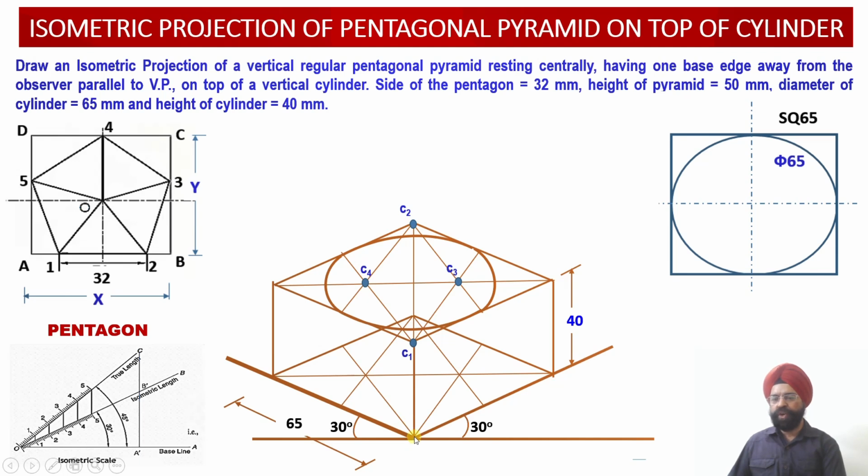Now once again our point of attention is this minor diagonal. From the first corner of the minor diagonal, two projectors have been drawn which will be meeting the midpoints of the opposite edges. So this is my first projector, and this is my second opposite edge corresponding to this corner. So the midpoint of this edge has been joined by a projector.